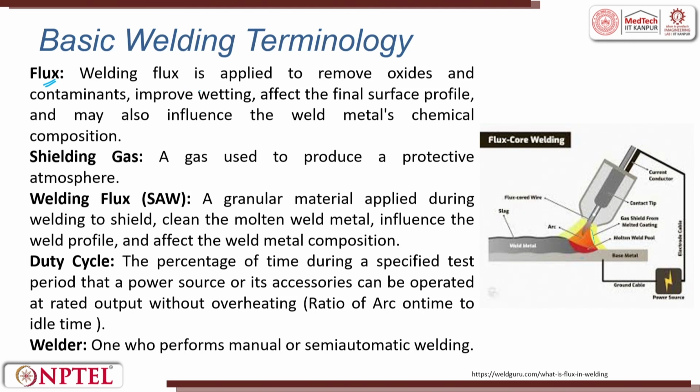Welding flux is applied to remove oxides and contamination, improve wettability, affect the final surface profile, and may also influence the weld metal chemical composition. So, either you protect it from outside, or you have reactions in the melt itself such that all the unwanted things are moved to the top.